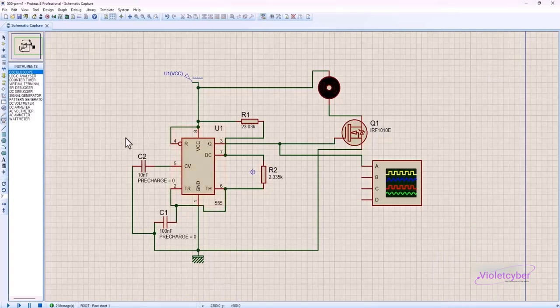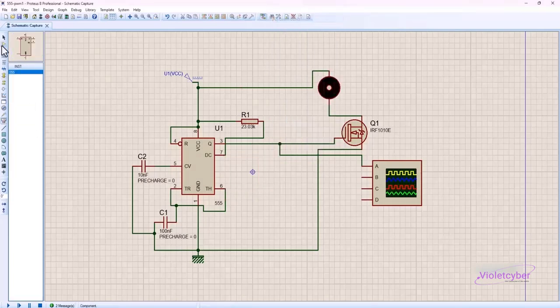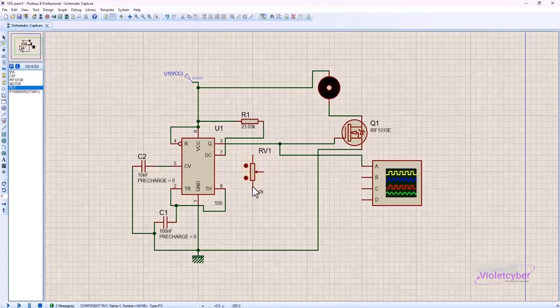Come on, let's control this. For example, now, if we come to control the amount of voltage that reaches 2, we can actually pulse. Without even changing the resistors and capacitors, let's change the value of the pulse. For example, how do I come here instead of this resistor? Well, instead of this, I'll put this here and replace it. I'll put a potentiometer like this. I'll connect one side to the same pin 6, the other side to pin 7 here, and the other side to pin 6 again.